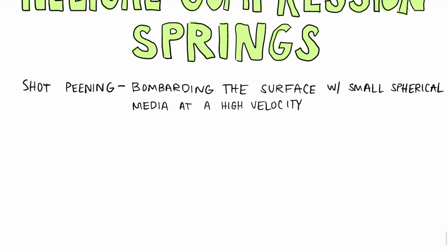Now, the best data that we have for torsional endurance limits of spring steels were published by a guy named Zimmerli in 1957. And what Zimmerli discovered is that no matter the size, material, or tensile strength of the spring, there was no effect of those variables on the endurance limit for wire diameters that are less than 3/8 of an inch. So the Zimmerli data give us alternating and mean shear strengths for peened and unpeened springs.